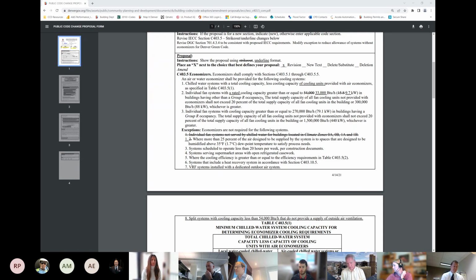If, like you said, Charles, it doesn't include the heat swap, then it's the same as a 4-pipe fan coil. What's interesting here is that the previous version of this proposal did include the heat swap ability of a water source heat pump system to be included in the regular commercial code as opposed to just the green code. Not having an economizer is less of a requirement than having an economizer. So if we're interested in that, the water source heat pump system has a much better possibility of actually swapping heat between the interior zones and the exterior zones.